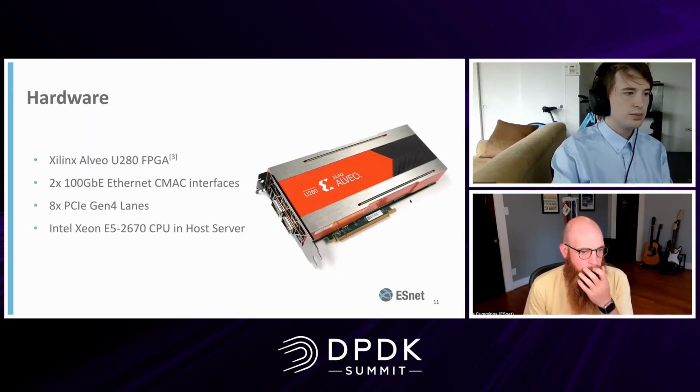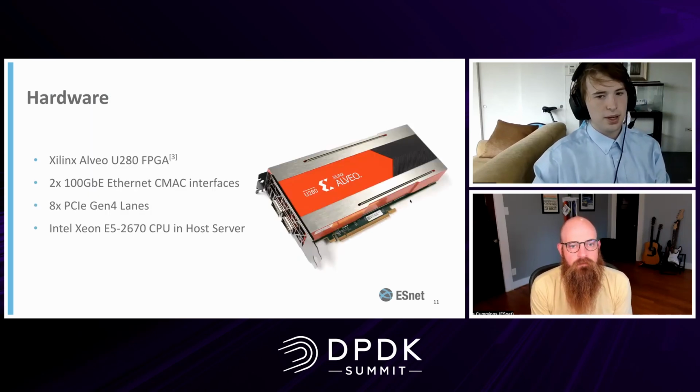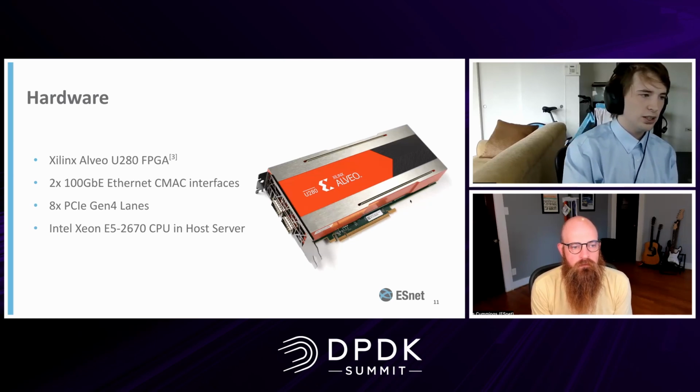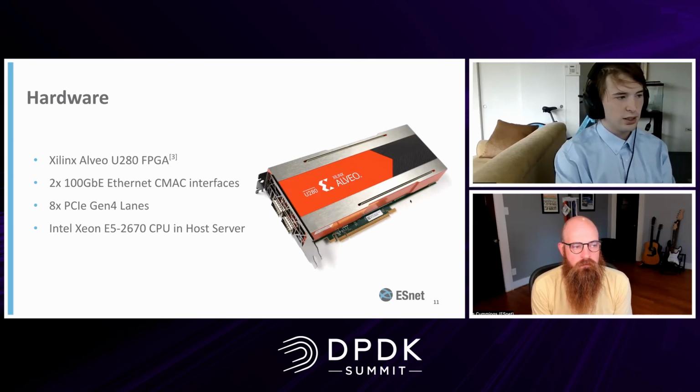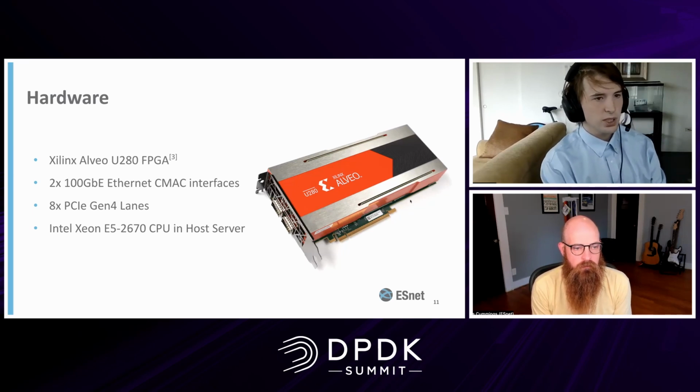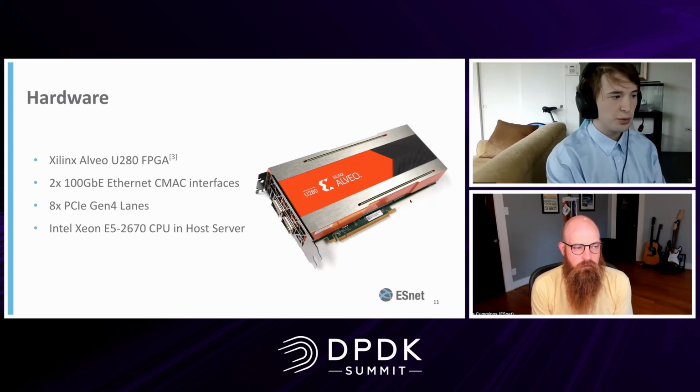So talking a little bit about the hardware that we use. We use the Xilinx U280 FPGA. It's got two 100 gigabit ports on it. Then it's got the 8X PCIe Gen 4. That's the PCIe that we're using for sending packets from the FPGA to the host, to DPDK.